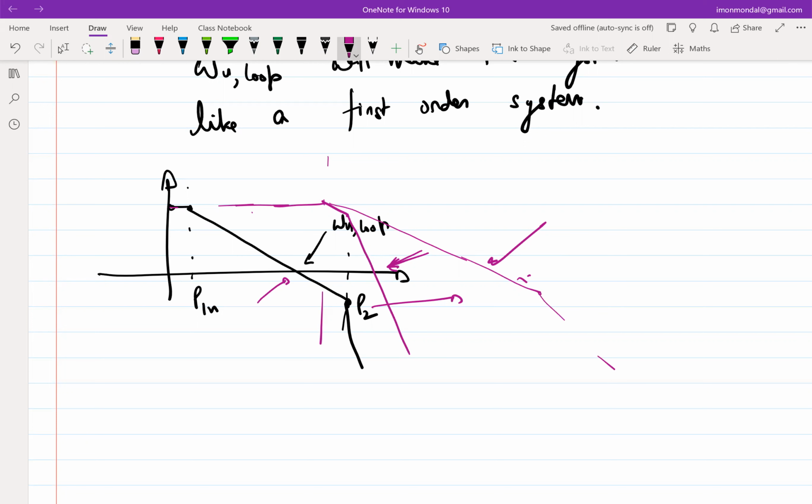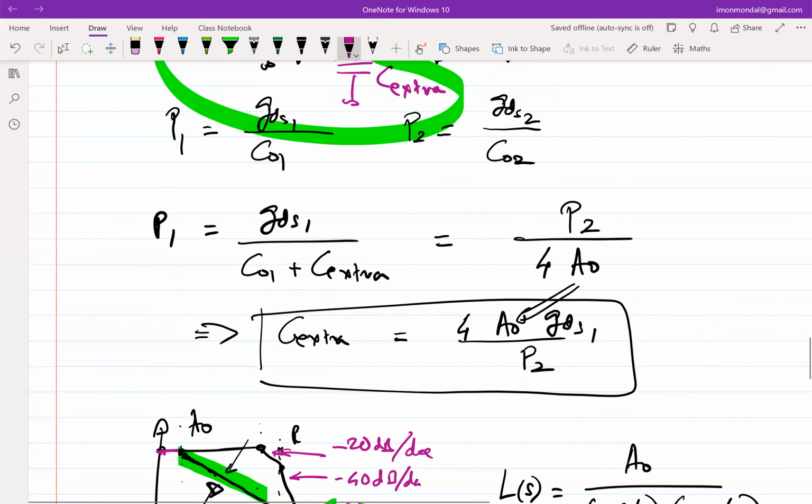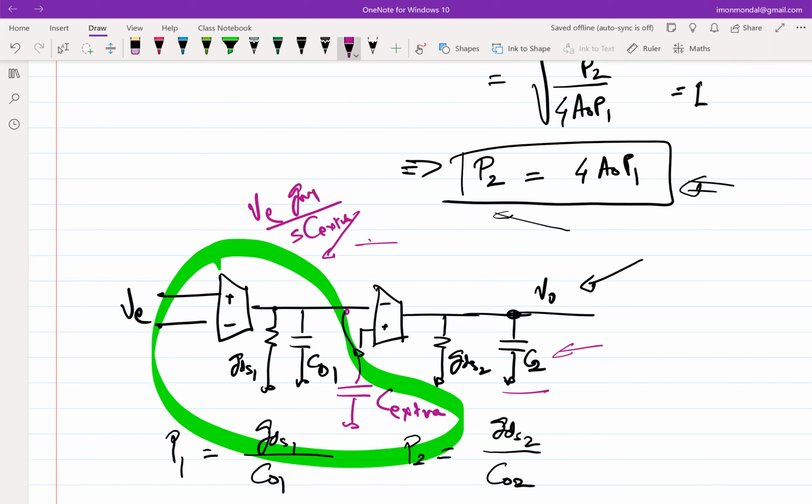Okay, so good point. What he is saying is that if you put two capacitances in series, it's likely to move poles away, right? Because C1, C2 in series is less than either C1 or C2. But one of the issues is you don't have access to this terminal of C2. It's a parasitic capacitance intrinsic to the device. If I had access to the terminal, I would have even opened it, right? No capacitance then. Since you don't have access to the terminal, you cannot do that.